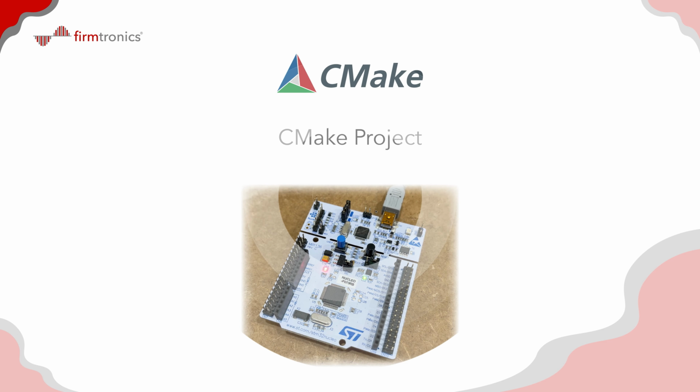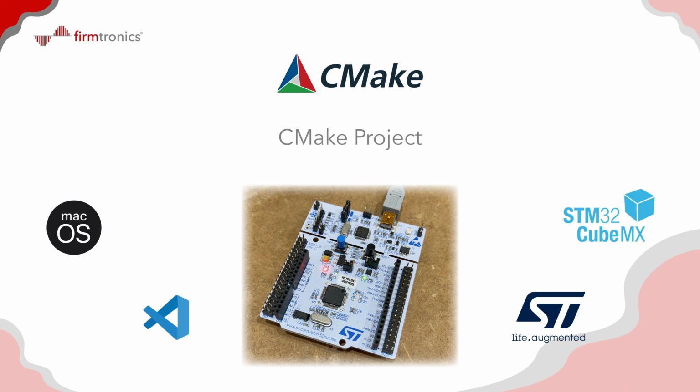So let's discuss the CMake STM32 VS Code extension approach in a bit more detail. CMake is an application that runs in the background to automatically generate a native makefile based on the current configuration of the project. The STM32 VS Code extension will automatically create the basic CMake files required to build an example project. This can be used as a good starting template.